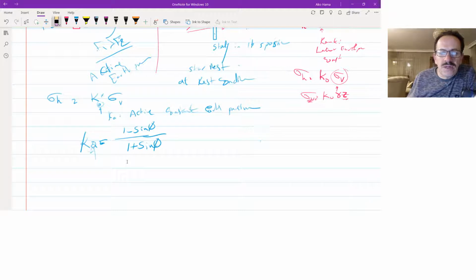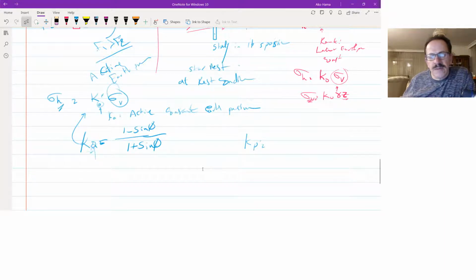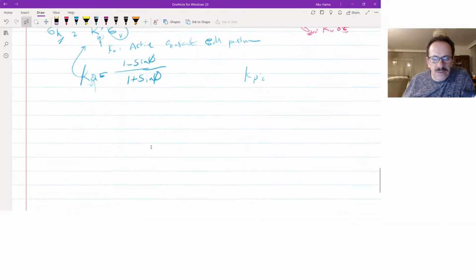So this is the Ka, and by the way we have the K passive, which is another case. We will just substitute the value of Ka here, and we will find the lateral earth pressure at any value. Again, sigma is equal to Ka gamma z, which then gives the value of the pressure and the depth.